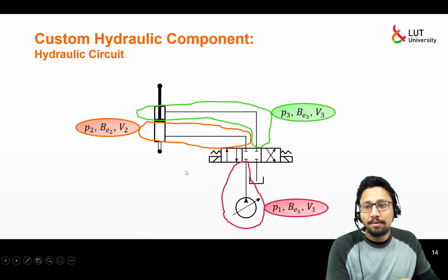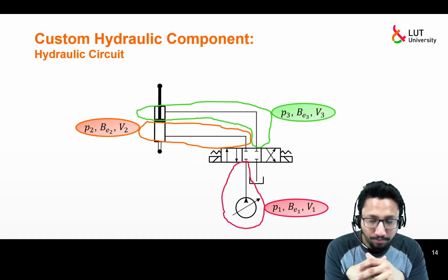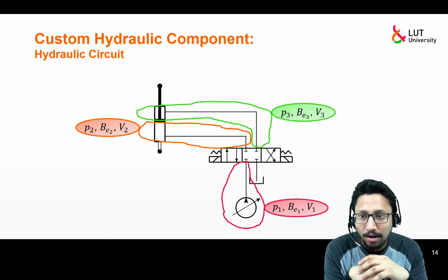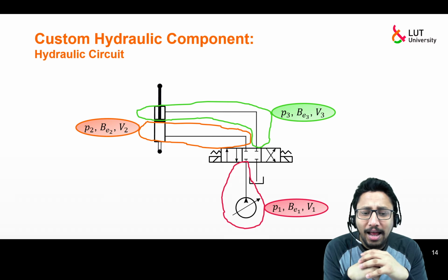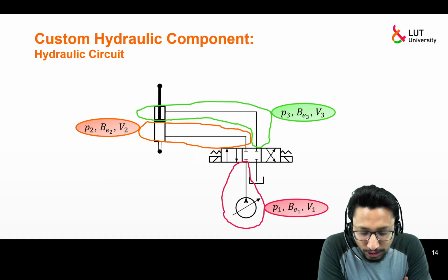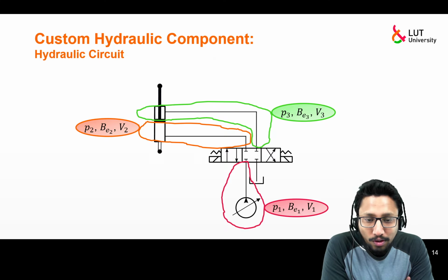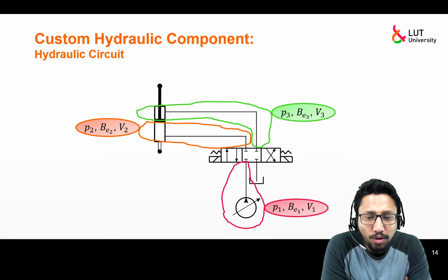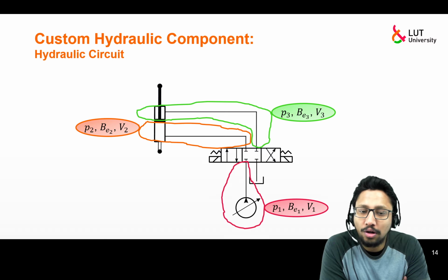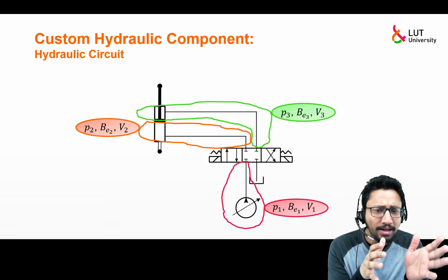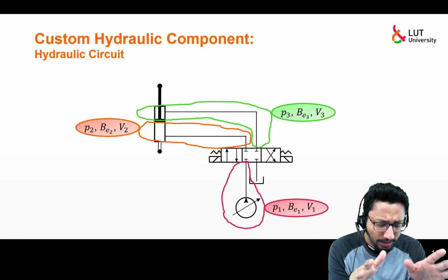Now before we move on to understand the hydraulic actuator and model it as a custom hydraulic component, let's first understand our hydraulic circuit. As you know, in this course we follow lumped fluid theory to model the hydraulic circuit, correct? This is a modeling approach which has been followed a lot in research work. With this you can model any hydraulic circuit very easily.